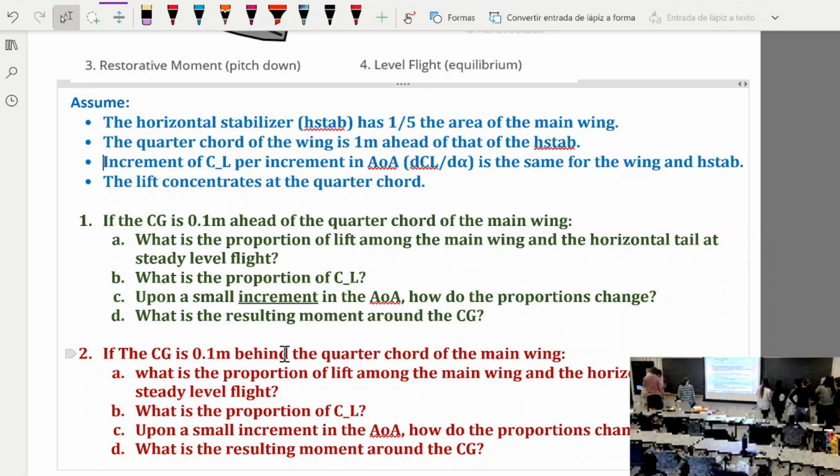It should be more positive, right? So just imagine negative 5 over 11, right? So imagine the CL of the tail is negative 0.5, CL of the main wing is plus 1.1. If you pitch up, let's say the 1.1 becomes 1.2. How does the negative 0.5 become? Sorry, a negative 0.4, right?